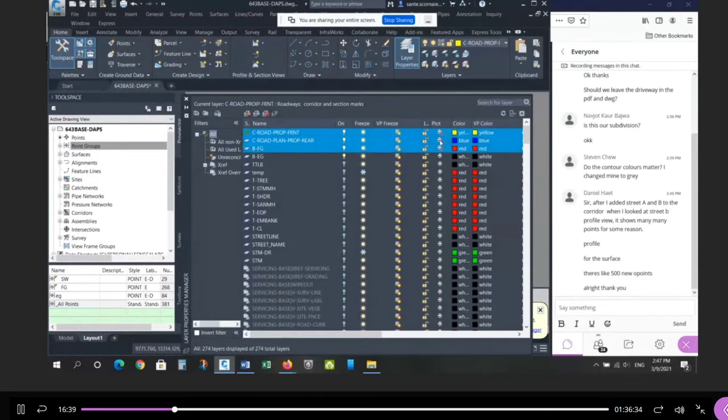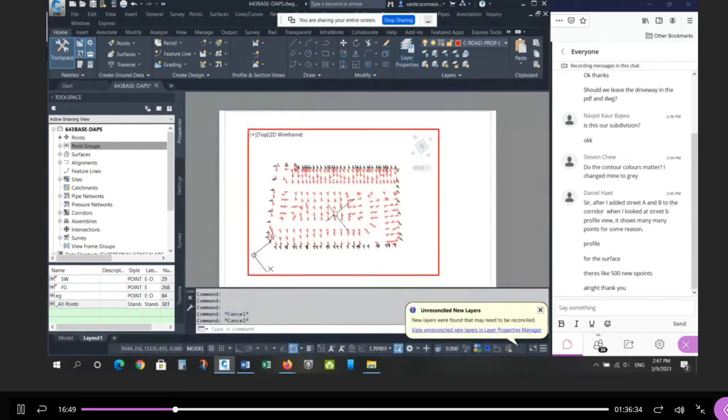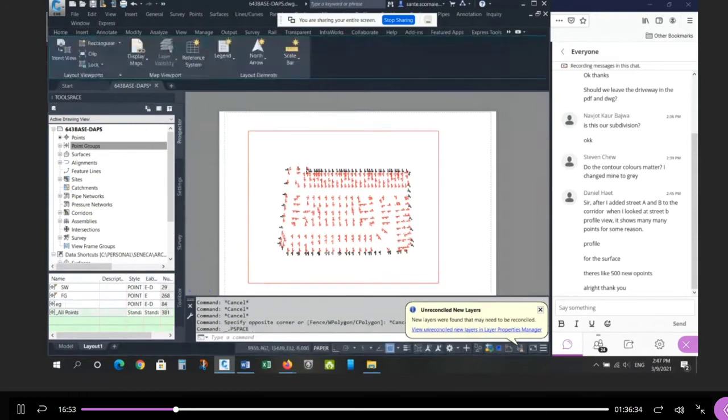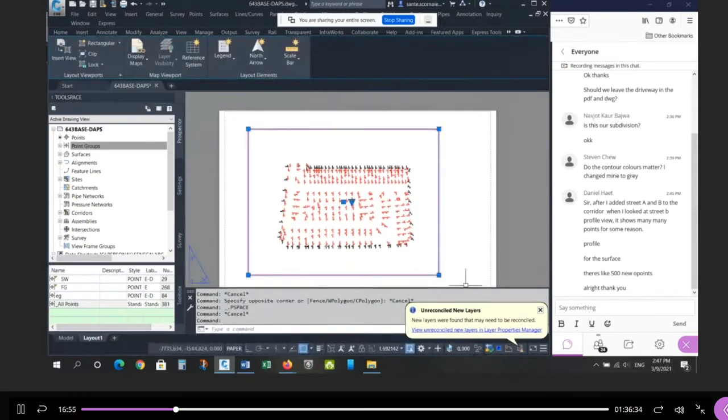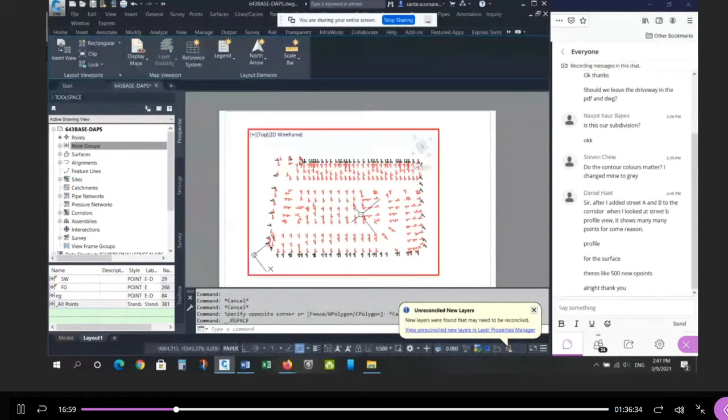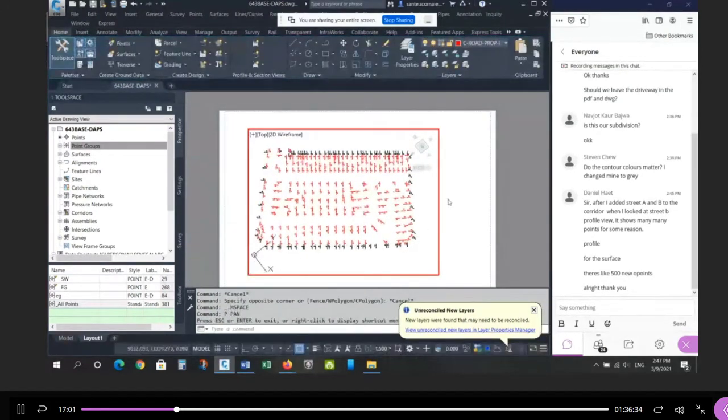Now, don't change the color in the actual model space. Do it in the viewport. That's what the VP stands for. So here I would make them all red. So on paper, it looks like you have 2 layers. Let's establish the scale. This will be a 1 to 500. And then you can pan around and fit it wherever it needs to be.